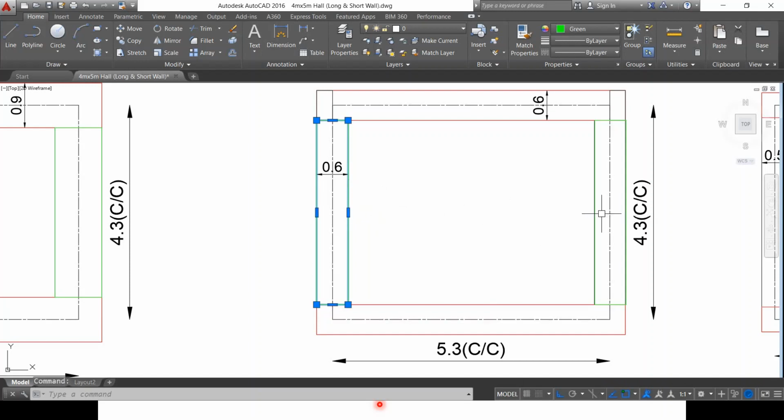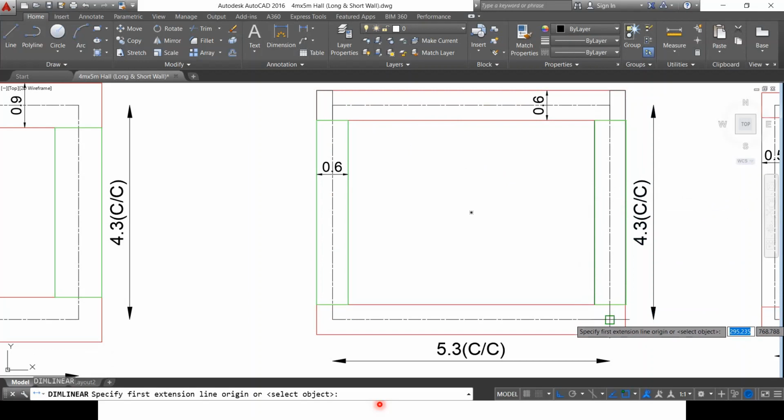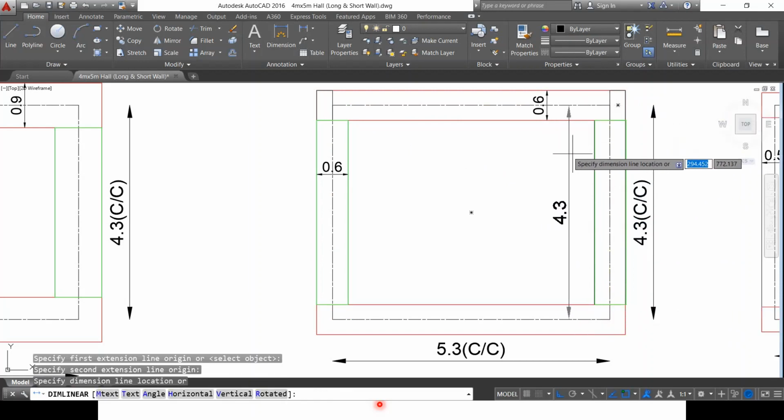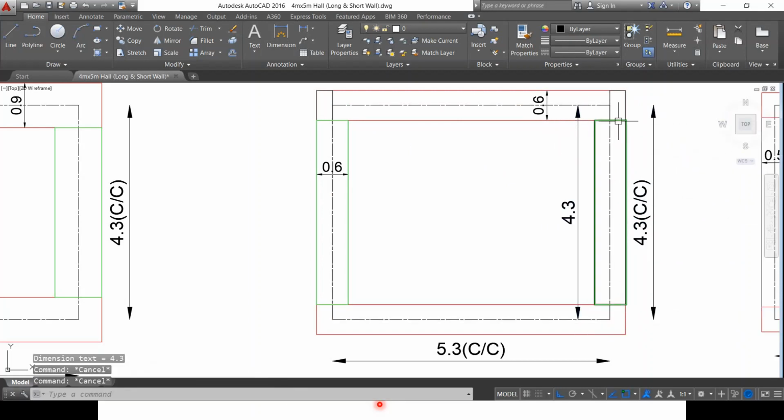Now the one indicated in green color is the portion where I have to go with the first layer of footing. But if we look at the center to center distance, which is shown as 4.3 meters, I need not lay the first layer over here because I've already laid it. So the one indicated in red color is the portion which is already constructed, or already laid. The foundation is already laid for the first footing, first course of footing.